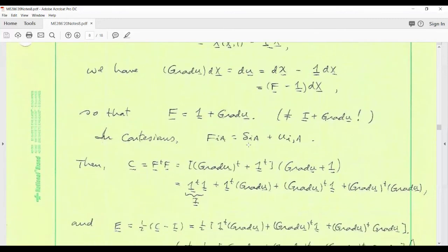In most of the literature, you will find this written as the identity plus the referential displacement gradient. This is where everything starts, this is where we first encounter the trouble. The shifter is not the referential identity or even the spatial identity. It's distinct. Right? So this incorrect expression typically uses the basis of linear elasticity, and it leads you to the incorrect conclusion that linear elasticity is defective on the grounds that it's not frame invariant.